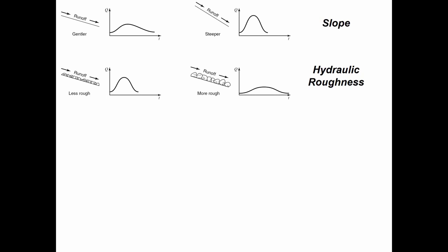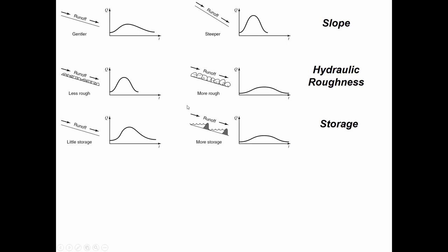The water is experiencing lots of friction, and so the velocity is going to be slower. And if the water is moving with a slower velocity, some of the water is going to be trapped down here in the cracks, in the pores of whatever the roughness is. Whereas when it's less rough and there's more smoothness, a smaller fraction of the flow is going to be in contact with that bottom layer. More of it is going to be up top with a higher velocity profile, and so overall it's moving more quickly in the less rough channel than in the more rough channel.